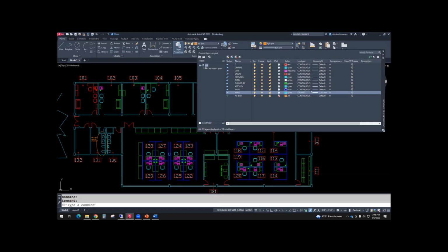All right, so even though I changed it in the Layer Manager, I don't see that change on my screen. So there is something called line weight hide show that we have to turn on. So we'll get to that.